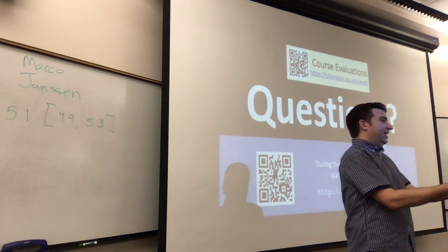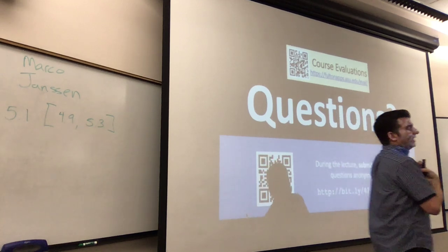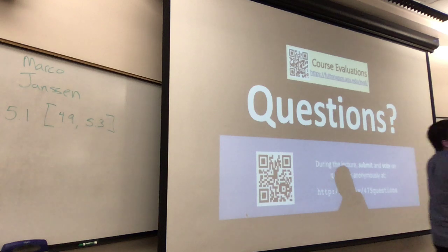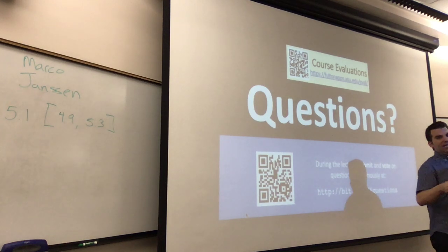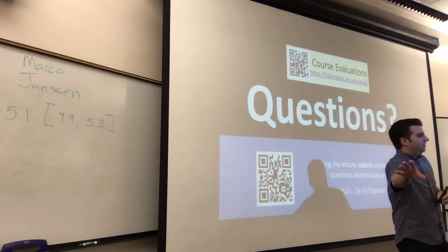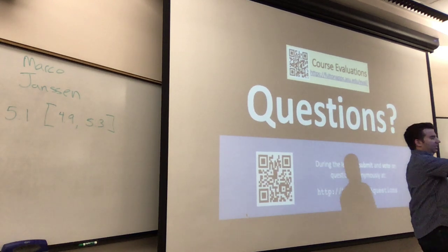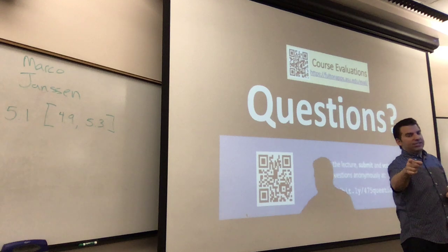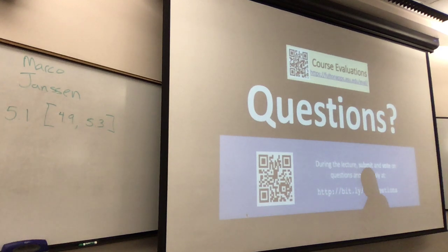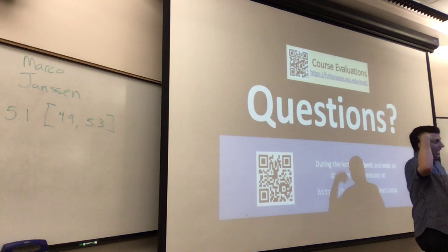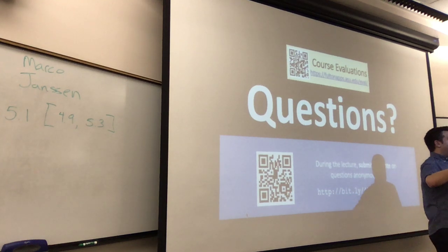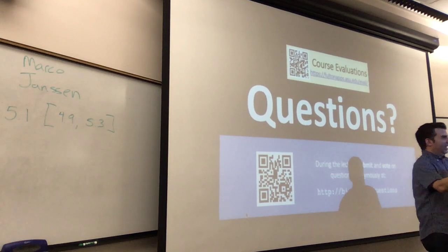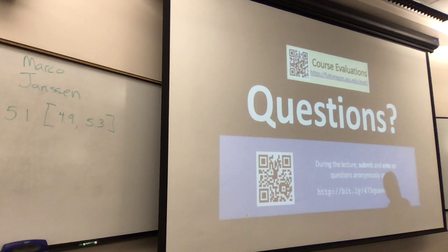If it doesn't, I wrote something incorrect in my code. Once you've verified your code is doing what your head is doing, validation is then asking: does your simulation model actually match what the real world is doing? If it doesn't, then you need to update the model in your head and then update the simulation model. So verification is about debugging, and validation is about linking back to the real world it started with.